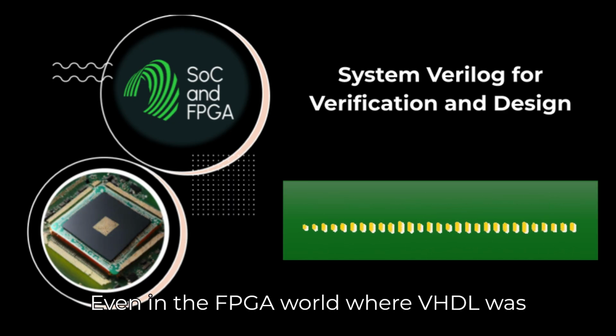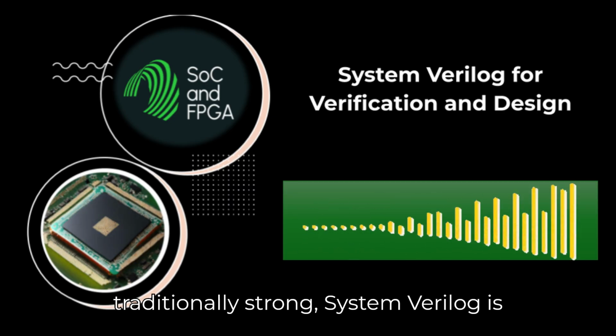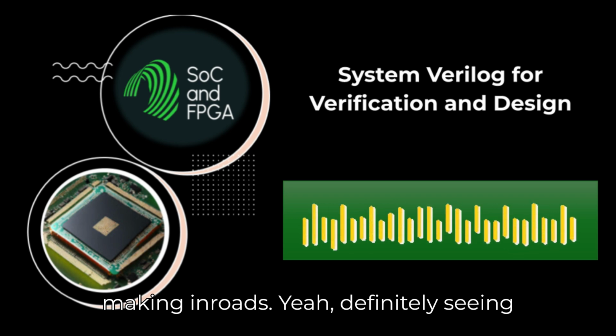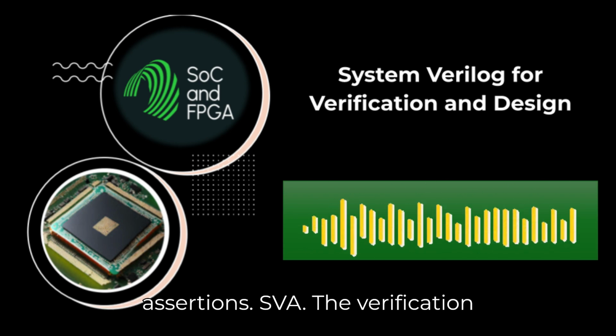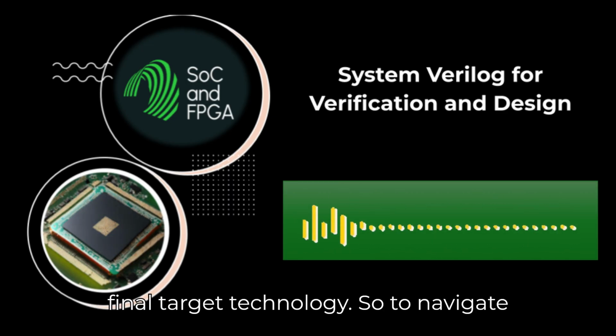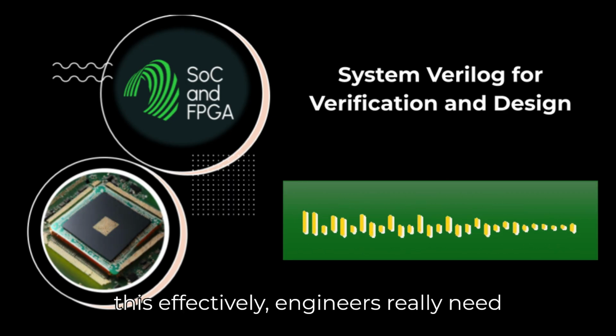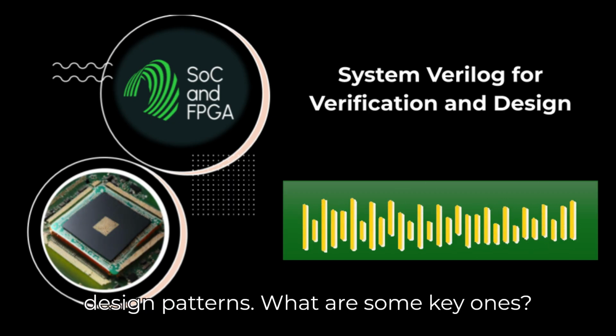Even in the FPGA world, where VHDL was traditionally strong, SystemVerilog is making inroads. Yeah, definitely seeing more interest there, especially for test benches and using SystemVerilog assertions, SVA. The verification benefits are compelling, regardless of the final target technology. So to navigate this effectively, engineers really need to stick to solid coding guidelines and design patterns. What are some key ones?